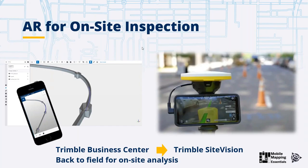Now, this is very true in case you are working in GNSS partially or heavily denied conditions. But we have seen that as soon as you are using the system in quite open areas, and we have customers facing these situations, the absolute accuracies are much better than that. We have seen customers with absolute accuracies in the range of 3 centimeters, so a few centimeters in 2D and height, but this would be more the exception than the normal rule, I have to say.